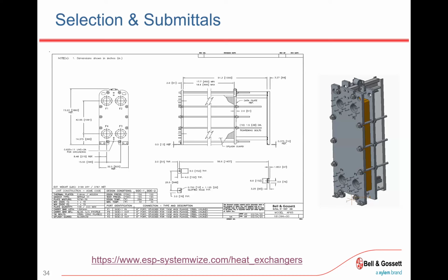So that's obviously great when you're looking at selecting your suction diffuser. On these, you don't want to have them throttled too far back for the design conditions. I would probably go closer to this 5-inch where it's 100% open. You don't want to start at your design conditions and really have that be at a 70% close. So you probably select this, and then from there, suction diffuser, you say, okay, I've got a 4-inch suction. What would make it easiest? We've got a system side, pump side, everything matches up to that suction size. So it makes it nice and easy for you.